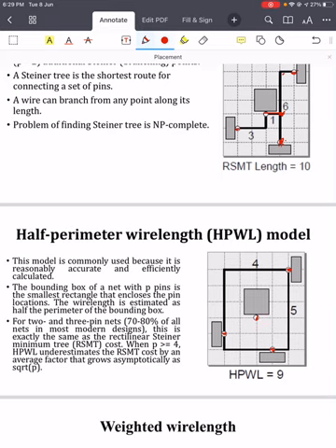We are going to consider a bounding box of a net with P pins. The bounding box is the smallest rectangle that encloses the pin locations, and the wire length is estimated as half of the perimeter of the bounding box.